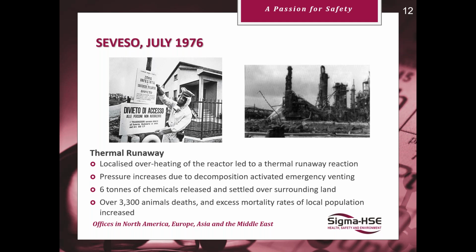In this particular reactor vessel, stirring was ceased as part of the shutdown. As other processes were also shut down, there was less demand on the heat from the steam. So what was normal heating at 190 degrees increased to about 300. With the lack of stirring, this had localized heating, which triggered a thermal runaway reaction of the reactor contents.